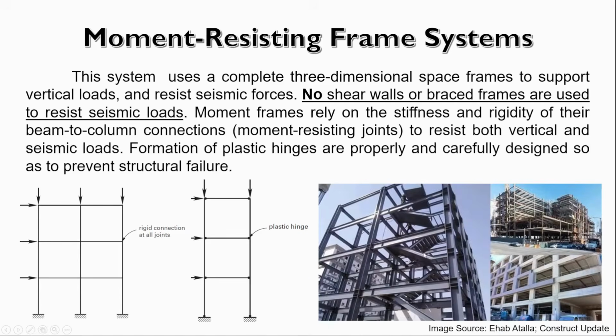So these are an example. This is just pure three-dimensional space frames. Okay, so we need to rely on the rigidity of the beam to column joints. So the hero here is the joint.